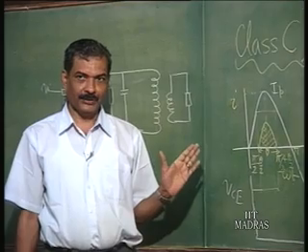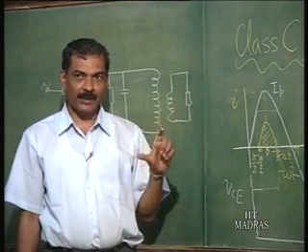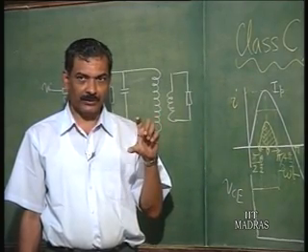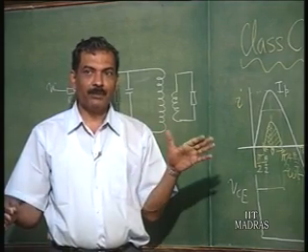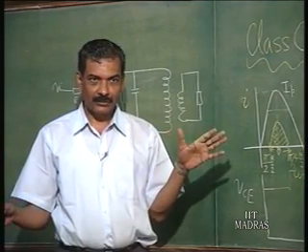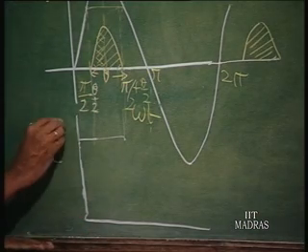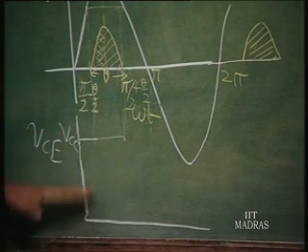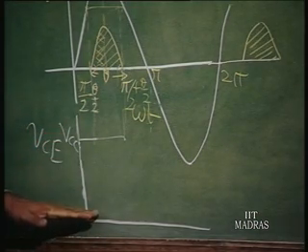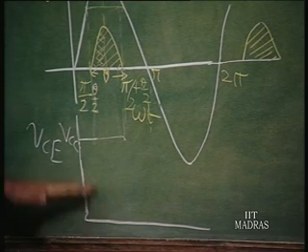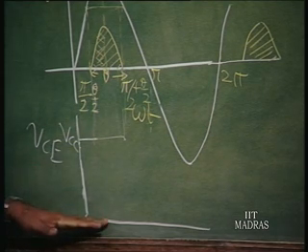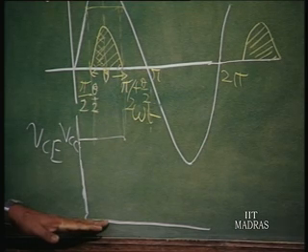So, the voltage that is going to be generated across the tuned circuit is going to be some Vp sin omega t. The Vp can reach as much as, since this is starting with VCC, almost VCC itself, the peak voltage. It is capable of generating that much value of the peak voltage. So, we will assume that it is almost VCC itself, the peak voltage.